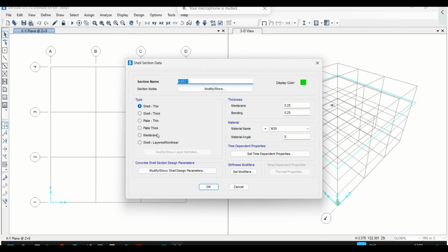In this case, we'll use a membrane. We use membrane, which has only in-plane stiffness, which is sufficient for most building-type structures. And our interest is to only transfer the loads applied to the floors to the supporting beams on the edges. So out-of-plane bending of the slab is not relevant for this analysis. The superstructure is a bare frame of concrete and beam.